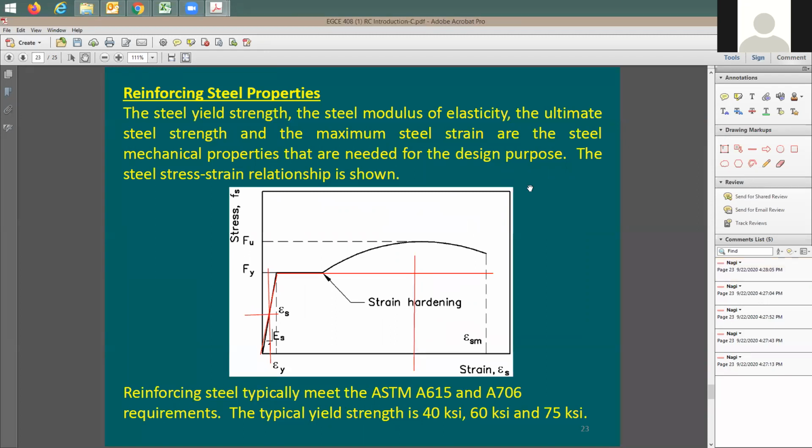Okay. The steel stress-strain relationship for tension and compression is the same. This is what you need to know. For example, if epsilon S was found to be here, usually epsilon you know is the same as E, right? So I'm going to say ES means epsilon S. You're doing the analysis, so go to the same stress-strain relationship. Find out epsilon S. You go with the straight line, and it turned out to be here. It's more than epsilon Y. You're done. Here's F sub Y.